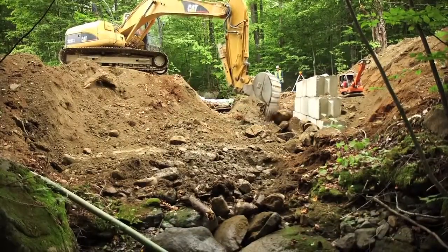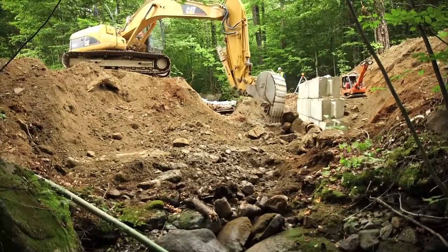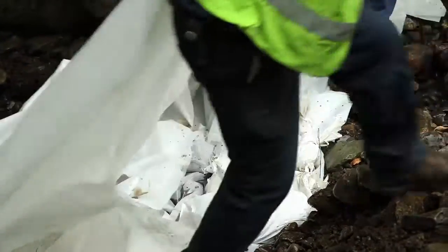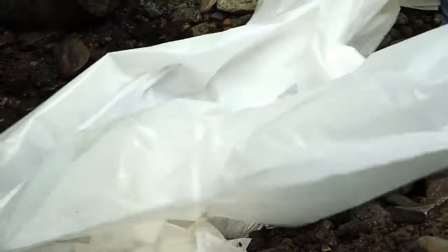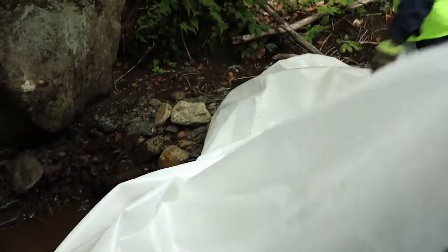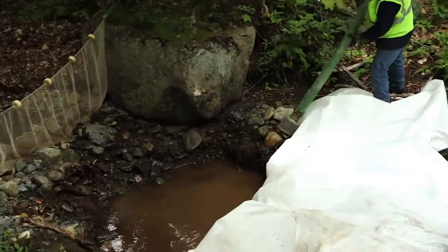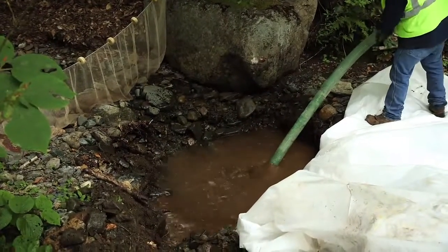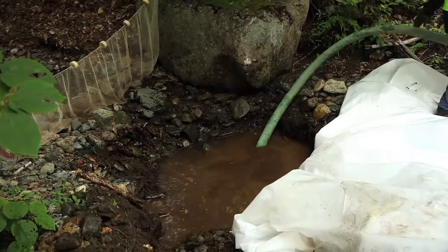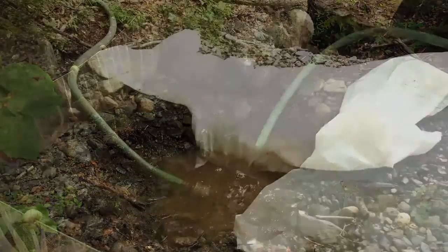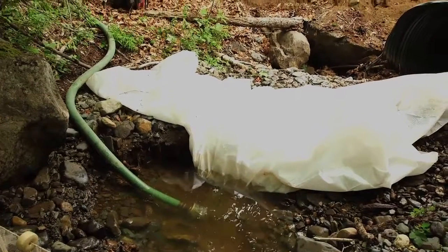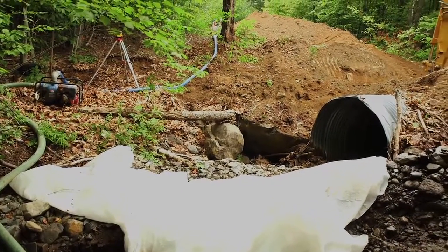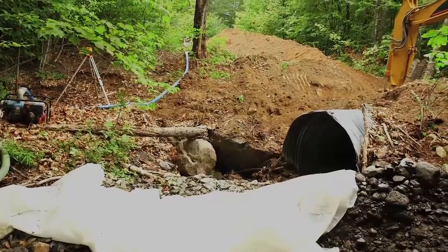The bridge was installed in August of 2013 when flows were low. Typically, a cofferdam is constructed both upstream and downstream outside of the anticipated working area of the site. The water pooled behind the upstream cofferdam is pumped around the site back into the stream below the downstream cofferdam. Since flows for this site were so low, an upstream sump with just a minimal cofferdam was needed to pool the stream flow to be pumped around the site.